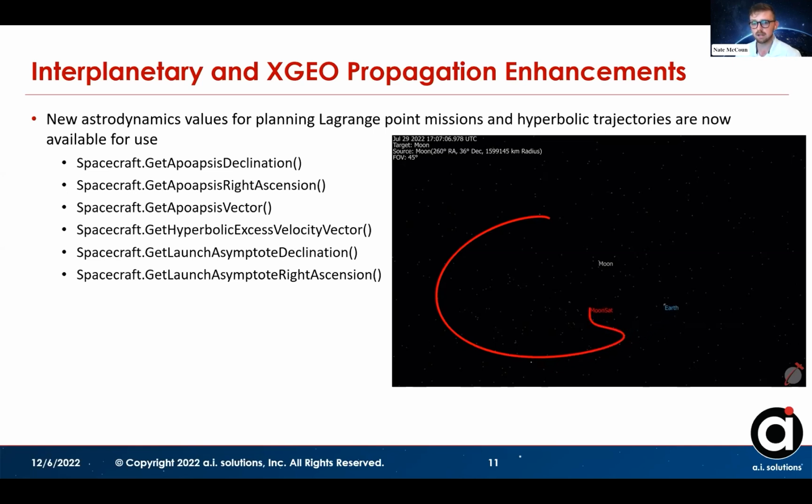And then a little more in depth on RLA: it is the equatorial east longitude from the vernal equinox. And it can be used when designing these departure trajectories to match the mission required outgoing V infinity vector to the specified launch site location.